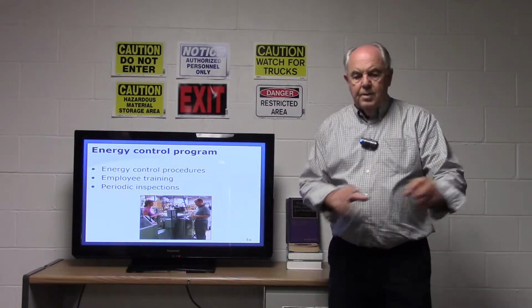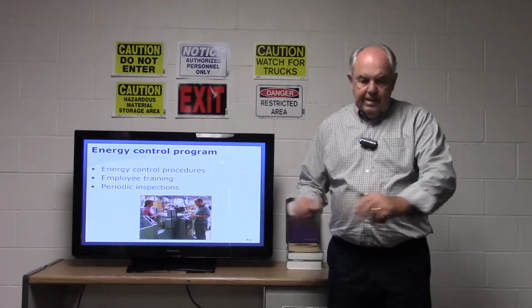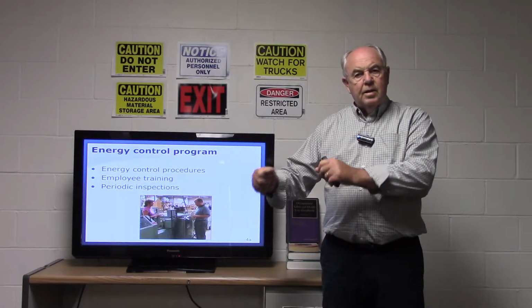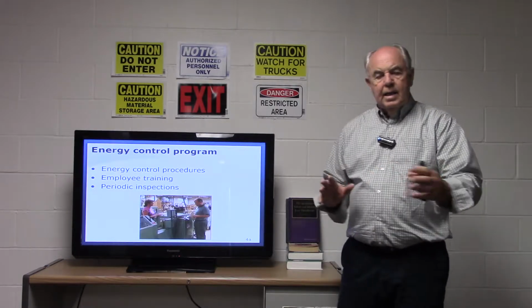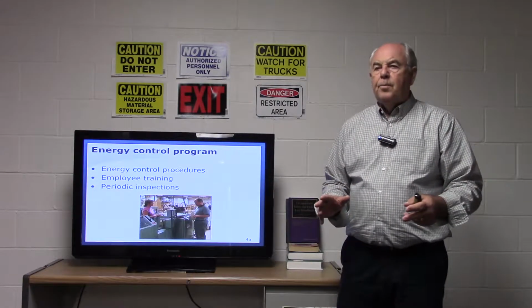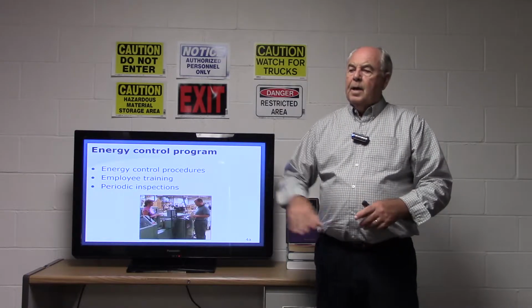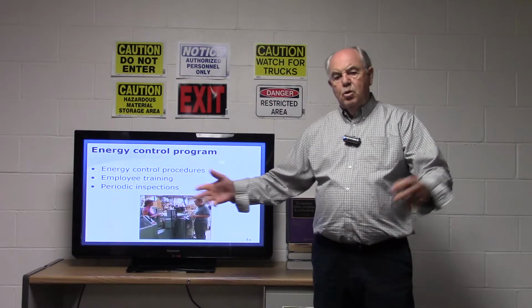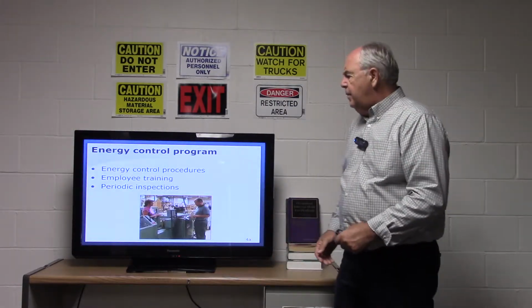So if you have 10 pieces of machinery, you'll need 10 lockout tagout procedures posted on the machine in writing, so that at any given point someone could review those, especially the authorized people, can go in and say, okay, here's the electrical disconnect, here's the hydraulic shutoff, here's the, it could be whatever, okay? So keep that in mind.